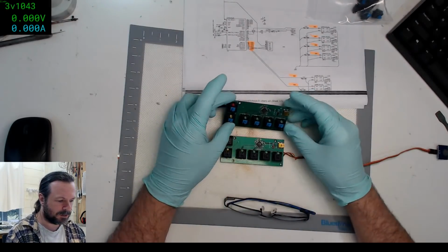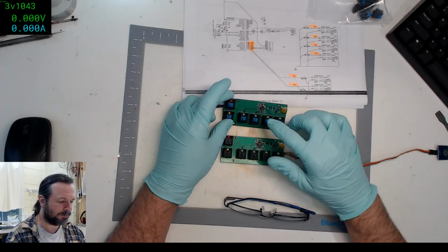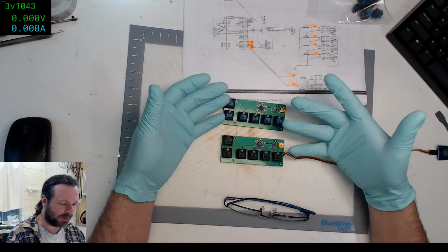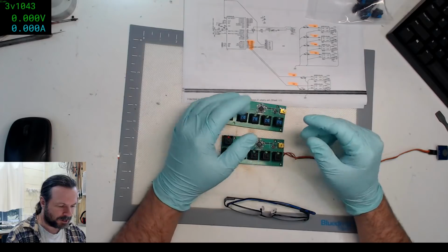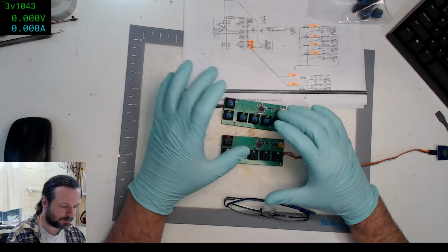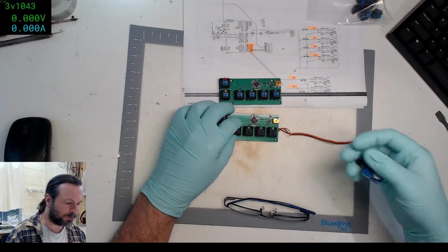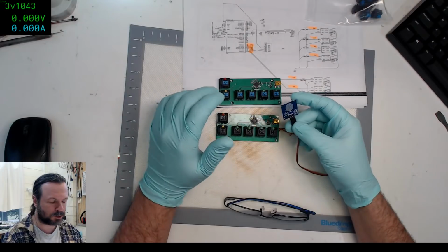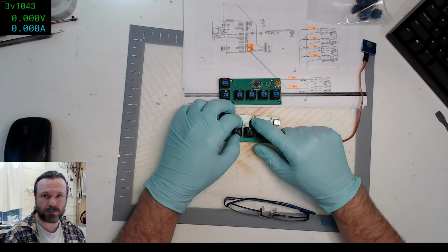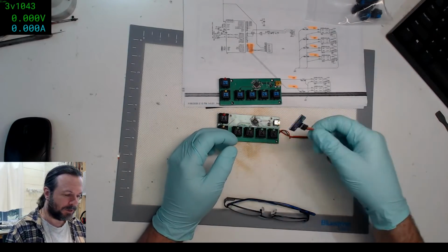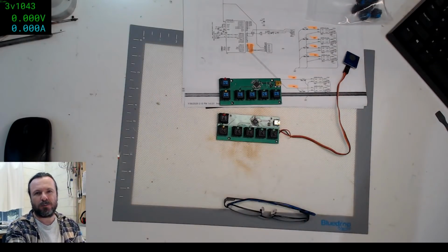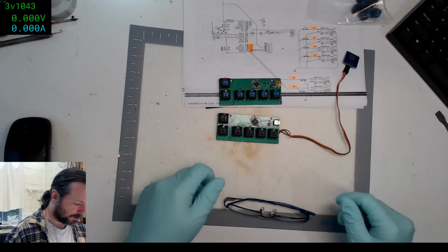Yeah, this here is kind of like an Elgato Stream Deck, except it's a very archaic looking version. It doesn't have any prettiness about it, but because of the way the switches are done electrically, it's not compatible with me just simply wiring one of these in as an alternate switch. So I have to physically remove the switch and then reprogram the chip so that it understands how to handle an active drive type line. Essentially, I've just got to disable the pull-up on that particular trace.